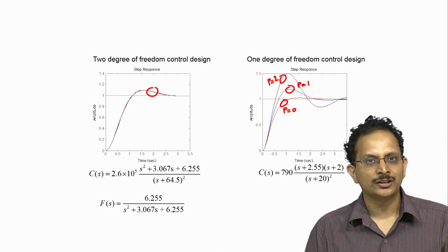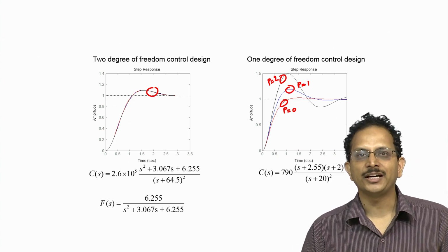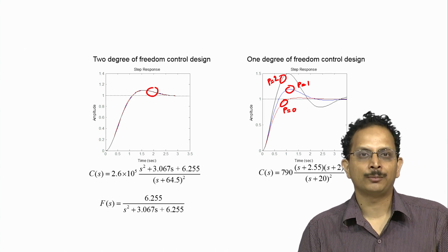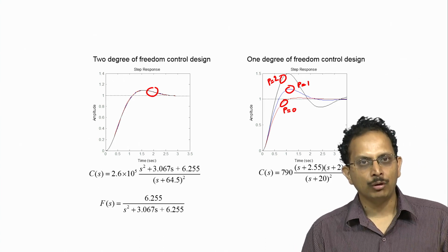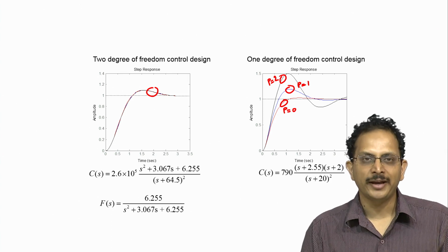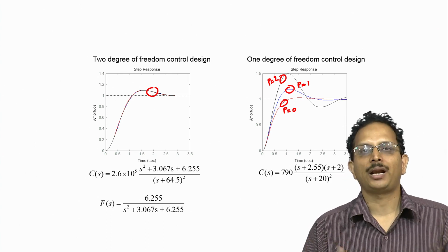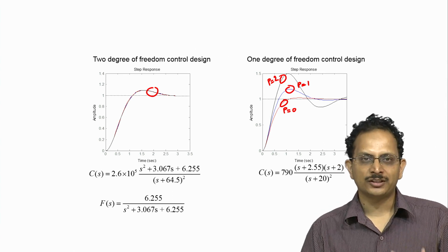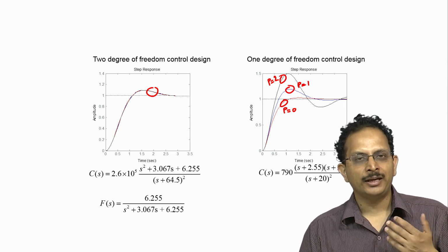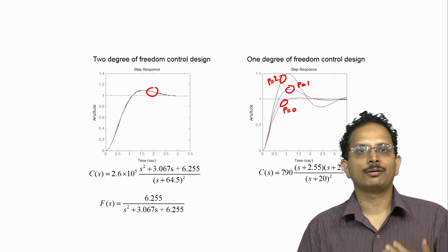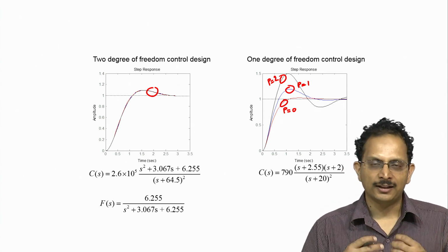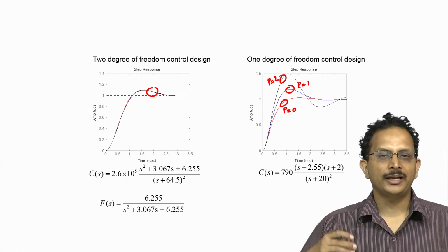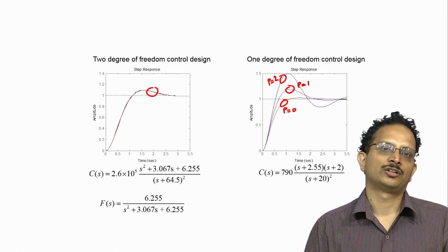What we shall do next is to see how we can design a feedback controller with once again 2 degree of freedom control configuration that will allow for achieving robustness against variation of more than one parameter of the plant. For instance, in the first case we shall consider the variation of the plant's gain as well as its pole position, and in the next case we shall look at the variation of the gain along with the variation of more than one poles of the plant.